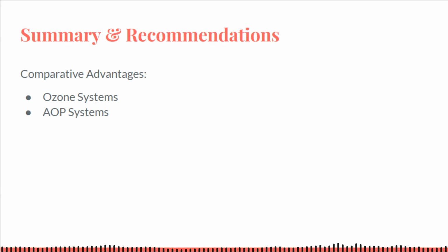8. Summary and recommendations. Comparative advantages, ozone systems: proven technology with decades of use, excellent at oxidizing chloramines and organic waste, resulting in clearer water and reduced chlorine demand. Generally simpler and cheaper than AOP.